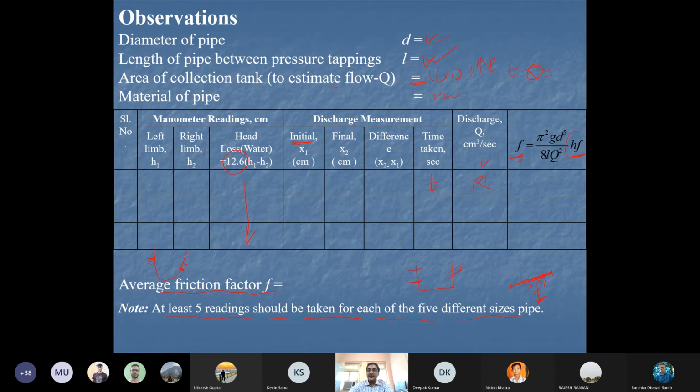But certainly, there is corrosion in the pipe, and that will change the friction factor with the time of the pipe. That is why it is called the shelf life of a designed system. After certain years, we need to change it, or whenever more head loss is generated, we need to change it because that requires more energy to supply the liquid. Is that not so? Yes, sir. So that is the simple idea.